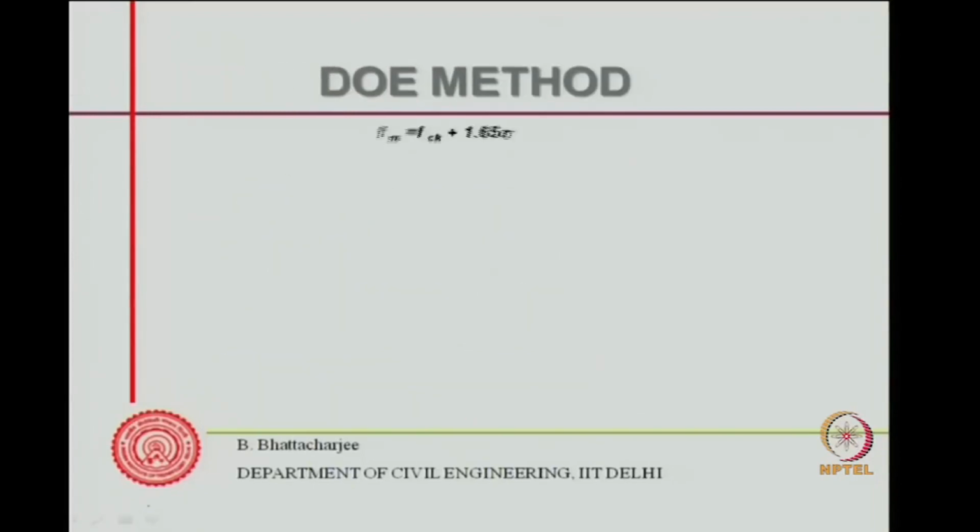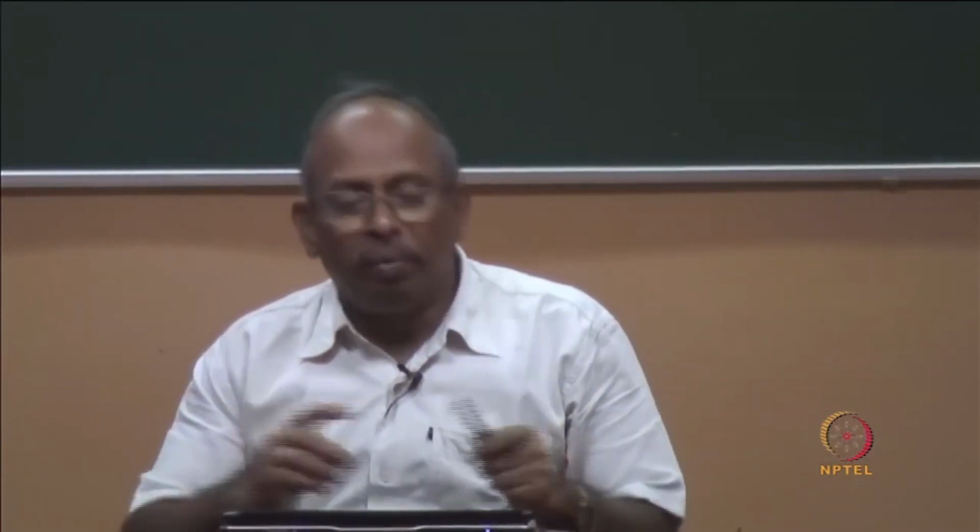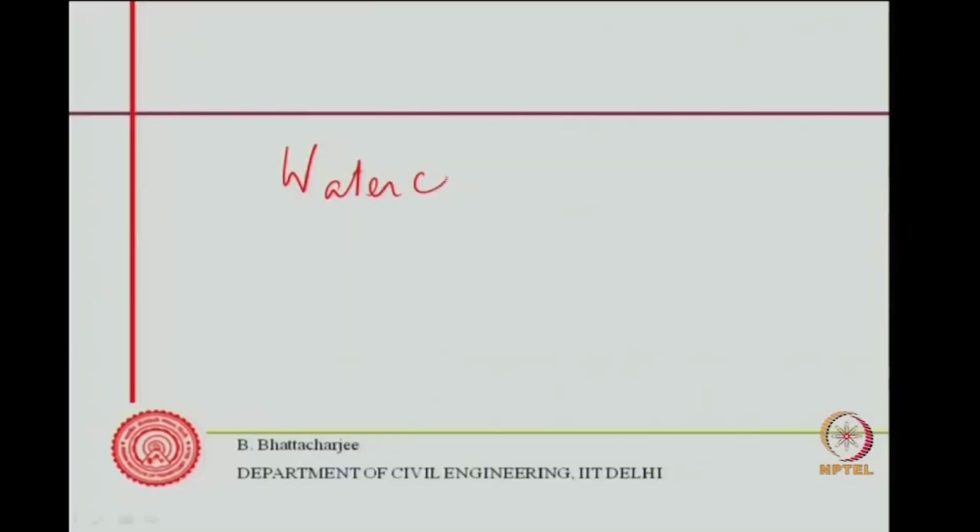Now there would be some site correction, because the water content at the site would be less, the water content of the aggregate will be somewhat less, somewhat more. So, there has to be some correction at the site. So, if the measured water content is known, let us say the water content of aggregate is WAGG, SSD absorption is WSSD, right.